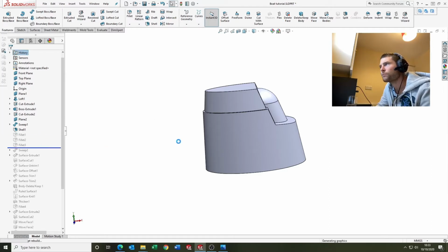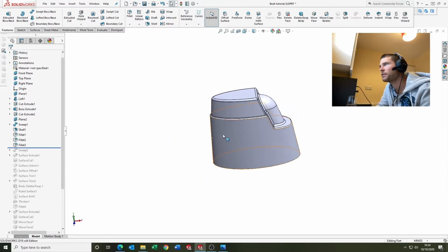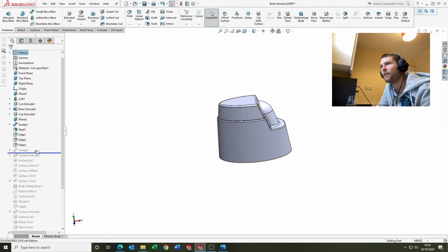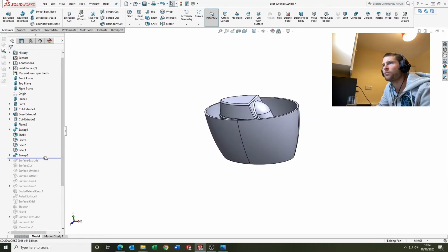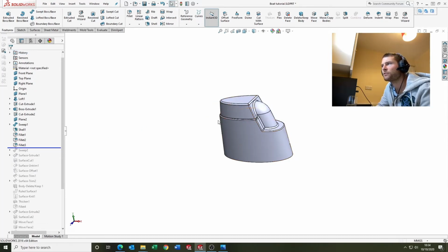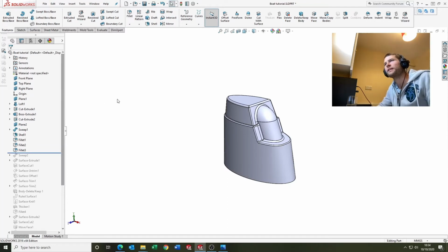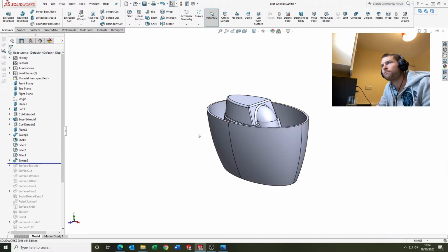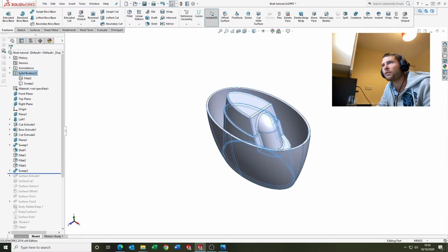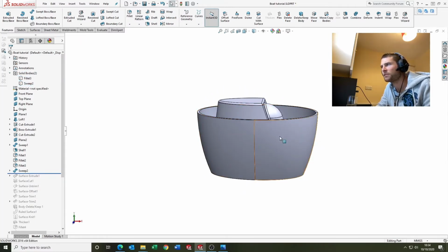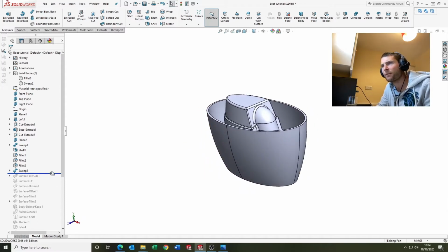So we've added some fillets in there to make it look nice. And then we've gone to the sweep. At this point, this is the first step, and this has created the first body in the modeling. This is a bit of multi-body part creation. Notice I haven't merged them, because I decided there's more going on with this, and we'd use this to build the next part. So I decided to keep it separate at the moment.